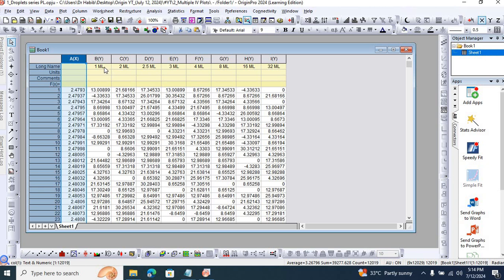This is excess gallium dose for metal modulated epitaxy growth of gallium nitride films. If you are interested more in that, study our metal modulated epitaxy growth of UID gallium nitride films from Professor William Allen Doolittle's group.